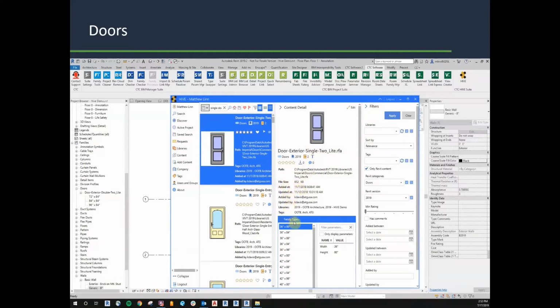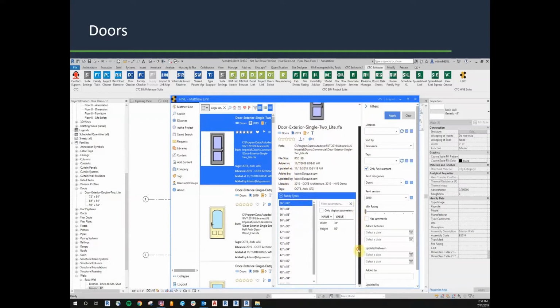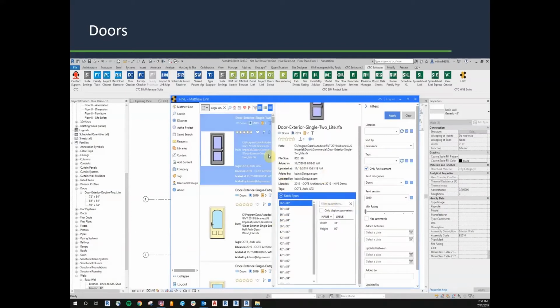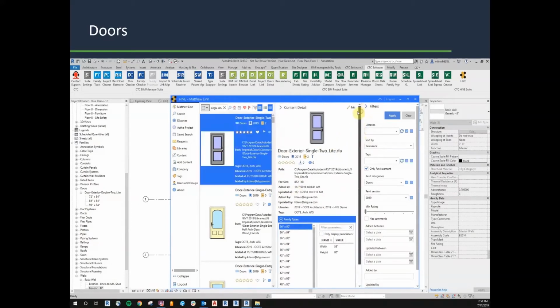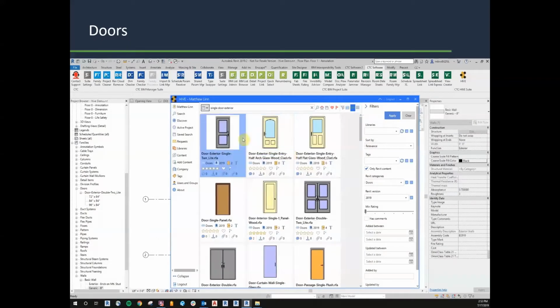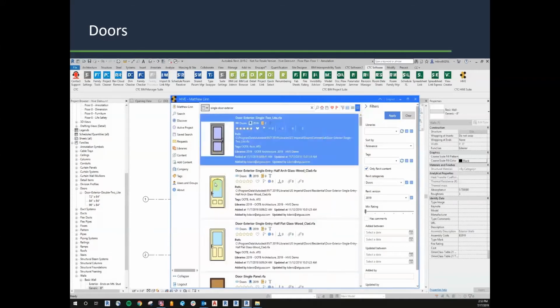It opens up that sidebar there with more information, has path, file size, all of the family types enumerated out. Kind of take a look at these types here. And you can go to a grid view if you wanted to after looking at the details. You can also go to a list view. That's our grid view there.